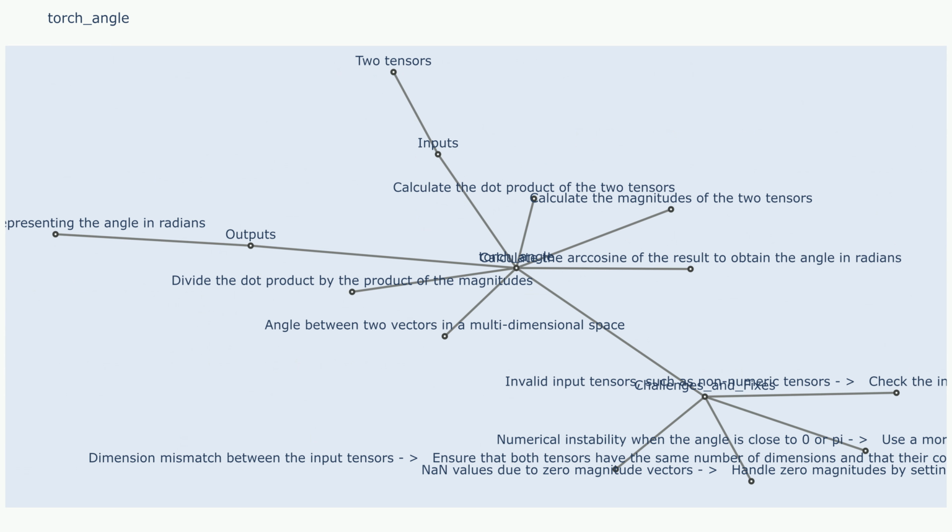An inconsistent torch angle can lead to an uneven weld bead, which can affect the strength and appearance of the weld. Sample use case that resulted in challenge 3: a welder welding a long seam with inconsistent torch angle, resulting in an uneven weld bead. Fixes to challenge 3: use a jig or guide.